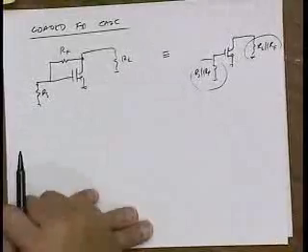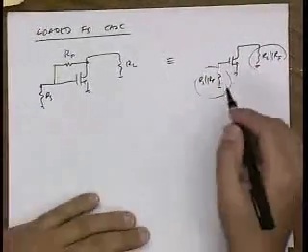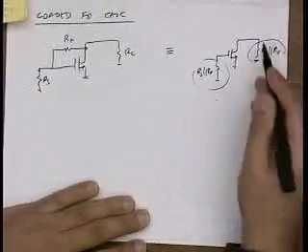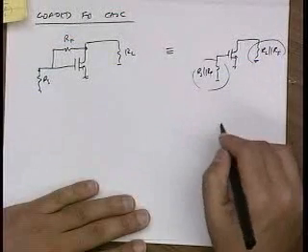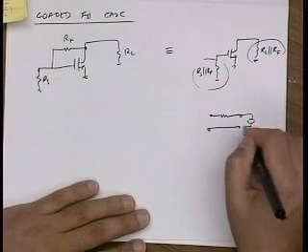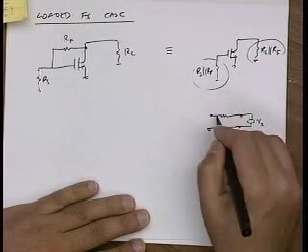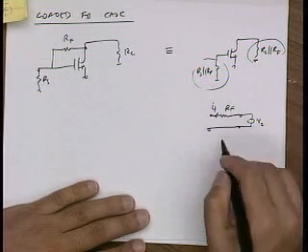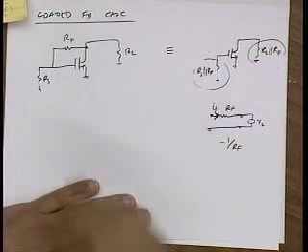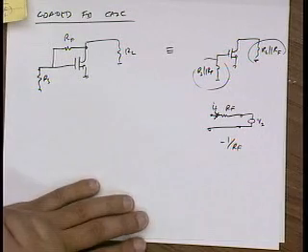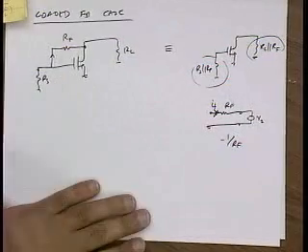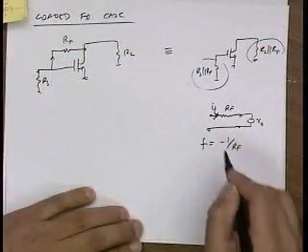But let's just check to see if this calculation works out. In this approach, this is my ideal forward amplifier. I neglect any kind of feedback in this amplifier, and then I assume that my feedback is unilateral. It takes a voltage at the output and feeds back a current. And so the feedback factor is just minus 1 over RF. Okay? If I wanted to subtract a current, I care about a current in this direction. So I want to subtract a current from the input. This is the current direction I should pay attention to. So this is the feedback factor.